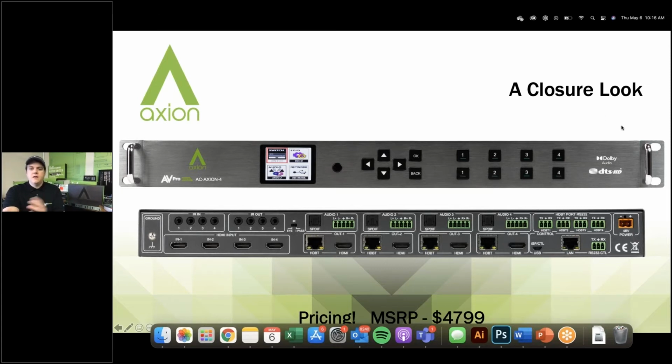And then how long will it take to switch between video sources? Always under 3 seconds for these. Depends how you have the scaling, depends what the source is, depends if it's 1080 to 4K. But we have made sure that it is as fast as we possibly can with hot plug detect, with all those different things that are going to still activate the HDMI sources correctly. But it is going to be under 3 seconds for sure. So great question, Federico.